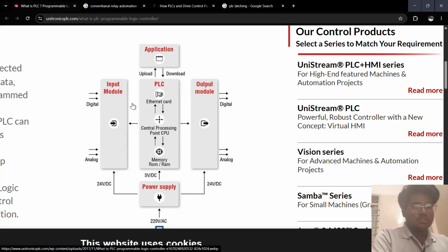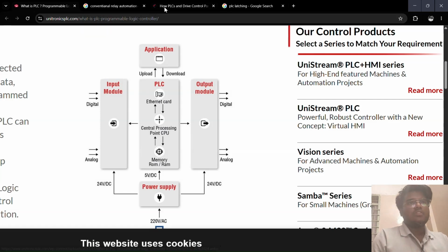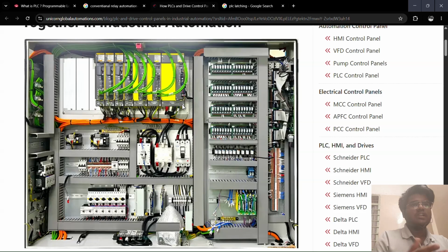First of all, a PLC is a programmable logic controller. In its architecture, there is a central CPU processing unit, controlled through input and output modules that are separated by a protective system, which withstands the high voltages of industry. The CPU processing runs on only 5 volts, while the input and output modules are 24 volts, or maybe 24 to 30 volts. PLCs are for industrial processes, integrated with conventional industry equipment, not for home use.